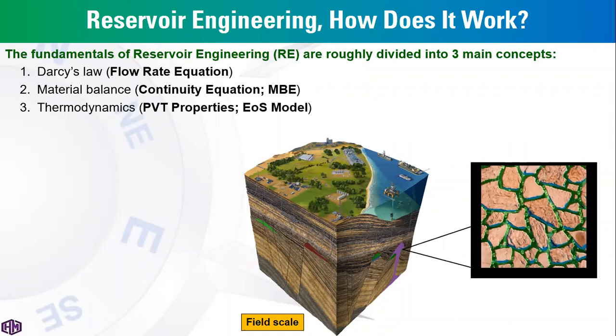Second fundamental is the material balance or continuity equation, because we have a specific subsurface volume or specific storage for such a reservoir. So the remaining volume at any time throughout the reservoir lifetime is the initial volume minus the produced volume.